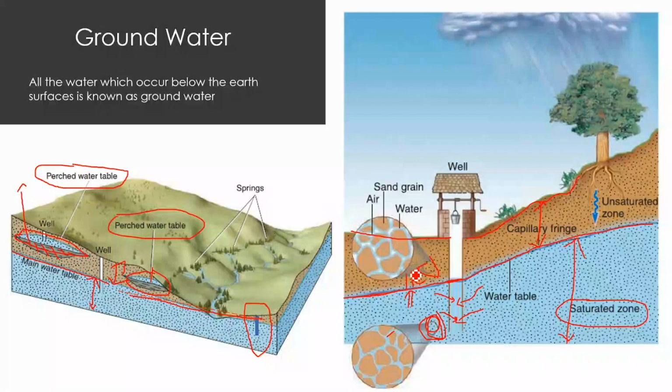So this is the plain region, but here is a hilly region. But if you see the depth of the water table, it is almost the same, but this also depends on the rock type and so on. But in general terms, the water table follows the topography. If you go to the hilly region, there also the water will follow the topography, but a number of other parameters control it. If all other parameters like rock types, porosity, and permeability are the same, then the water will follow the same topography, but depending upon the type of rock and its other properties, it may vary slightly depending upon the terrain.